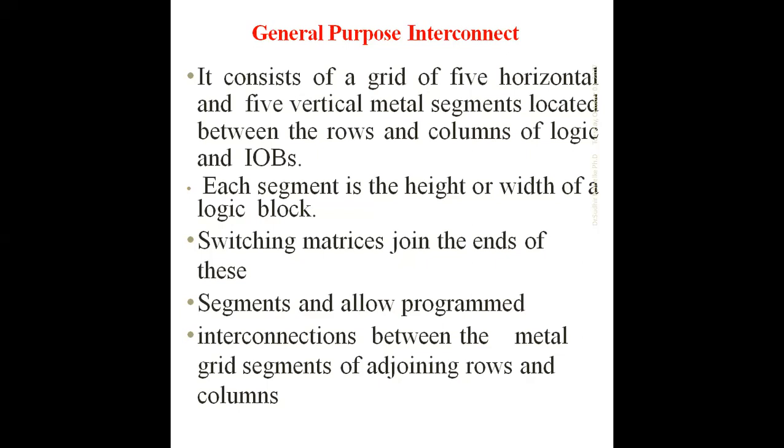Each segment is the height and width of the logical block, the same width and height as the logical block. The switching matrix joins the ends of these segments, and that switch has to be turned on or off through a program only. It allows programmable interconnection between these metal grid segments of adjacent rows and columns. Okay, we'll see one diagram.